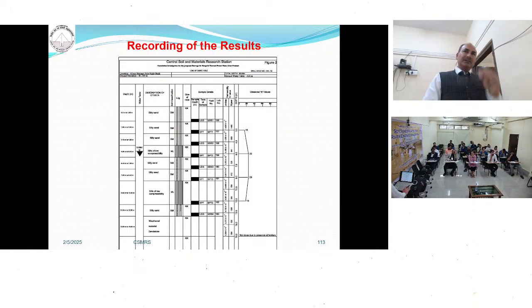Normally, let me tell you about only one thing about the borehole. Either you have to go to the full report, but only by looking at the borehole you can say what the results of your foundation strata are. Here everything is written. What are my SPT values? Then what are my permeability values?